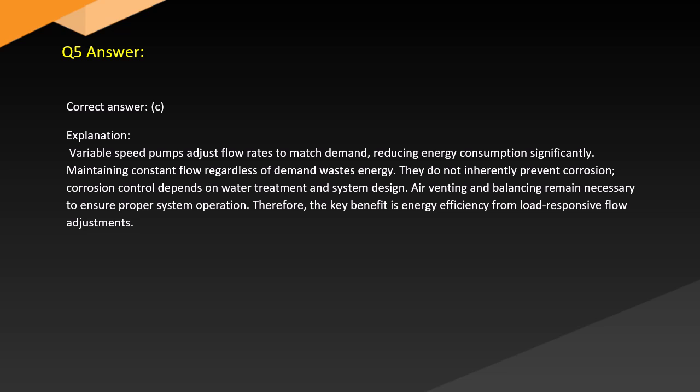Answer. Correct answer: C. Explanation. Variable speed pumps adjust flow rates to match demand, reducing energy consumption significantly. Maintaining constant flow regardless of demand wastes energy.